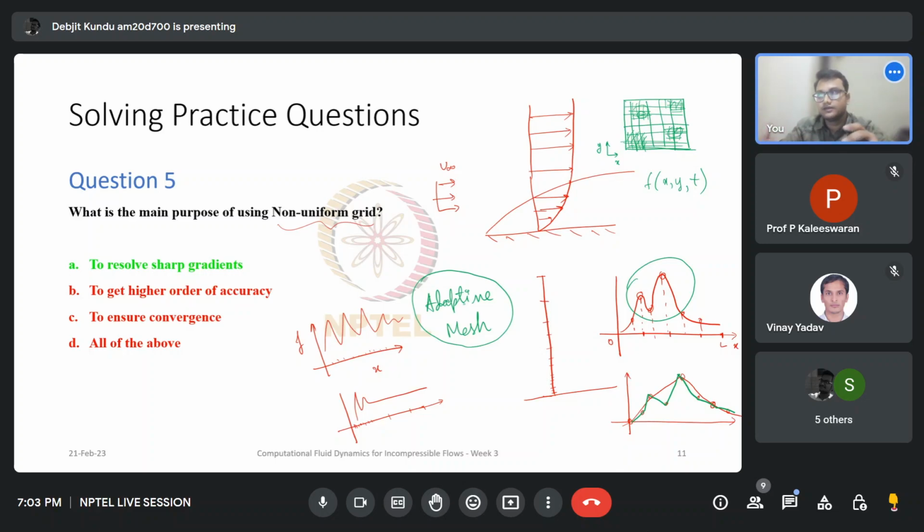And then, the opposite also occurs. Let's say in this region where you had very sharp gradients initially, that place has quietened down now. Then these closely spaced grids are not required. They are increasing your computational cost. Then these are unrefined as well. So this region again goes back to wide spacings.